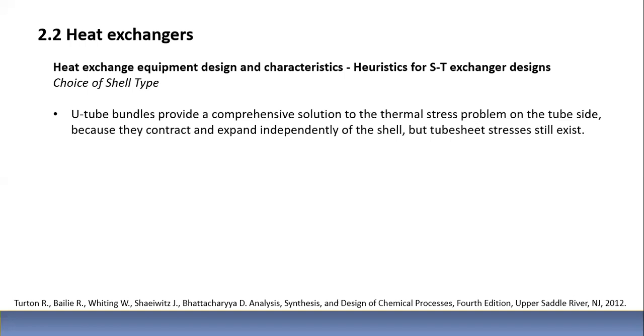U-tube bundle provides a comprehensive solution to the thermal stress problem on the tube side because they contract and expand independently of the shell. But tube sheet stresses still exist.